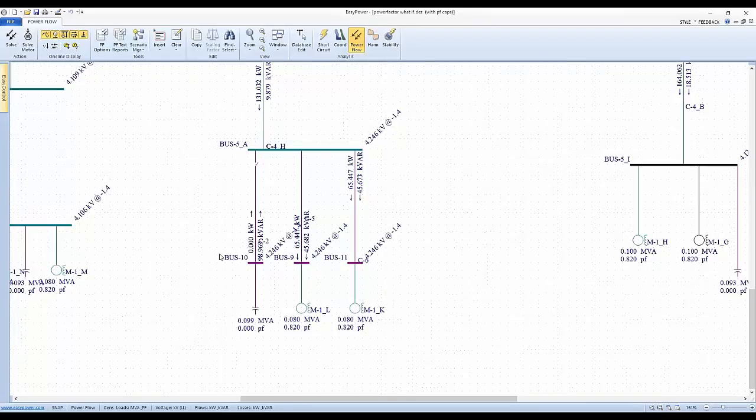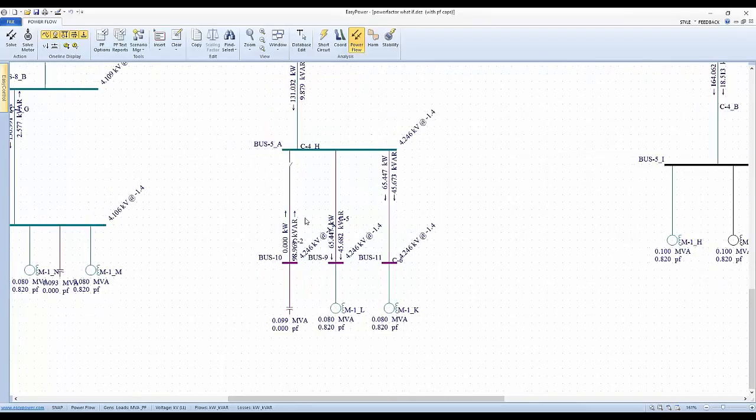So the question that's interesting in my mind is, where does that current go? Where does that energy go if it's not going up to the utility? We still have the same reactive current going through the capacitor, going through the motors, but now instead of going up through the utility line, it's going back through our capacitor.